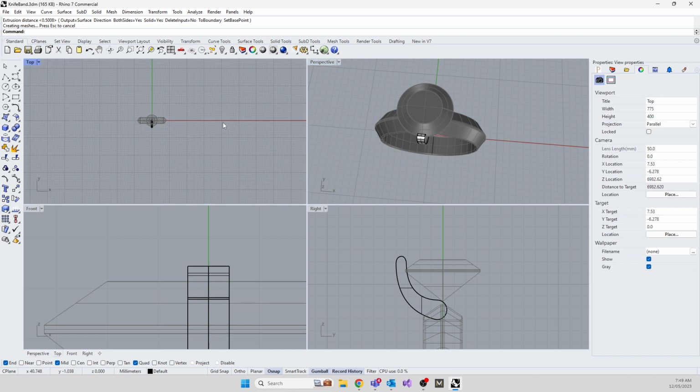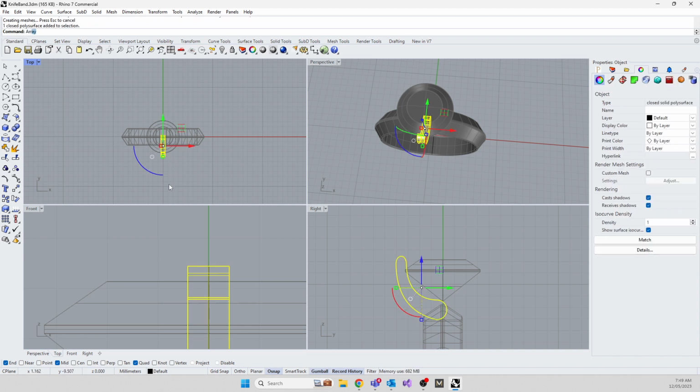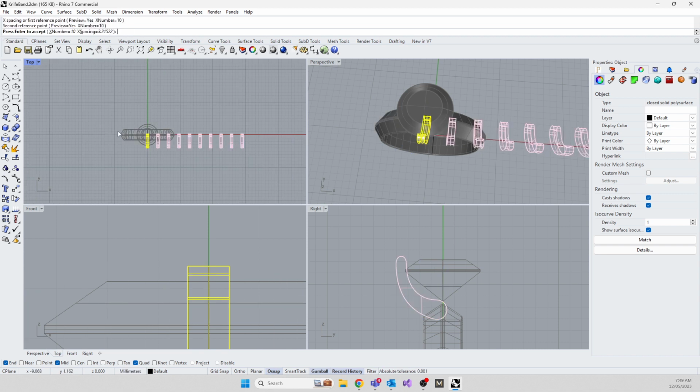All right. And so now we're going to do a new command you haven't really played with. In the top view, we're going to do array. Remember we did array and you could make something copy in multiple copies in every direction? All right, so like you could array this. Array is the same as saying lots of copies by a fixed distance. So in X, I wanted to make 10 of them. I only want 1 and 1, and my copy reference point is this. So I can quickly copy 10 things. All right, I'm going to press escape.